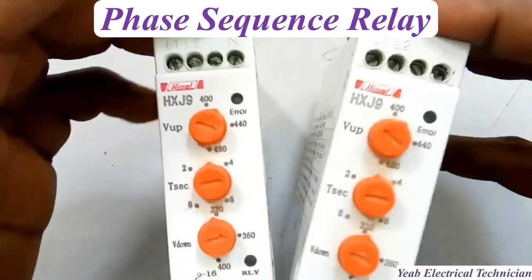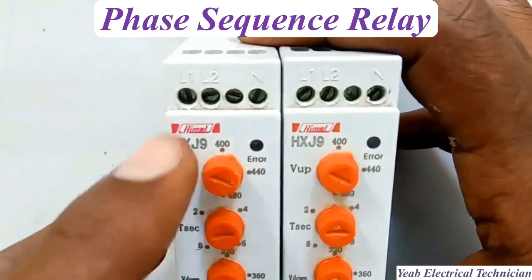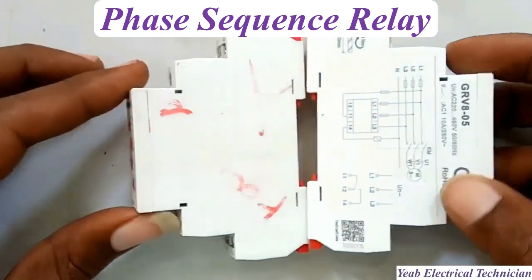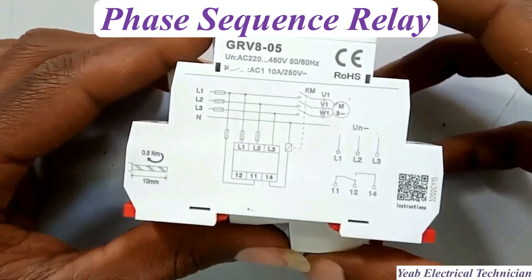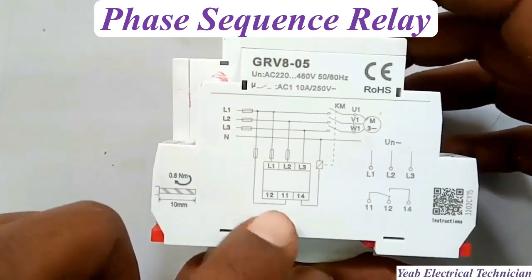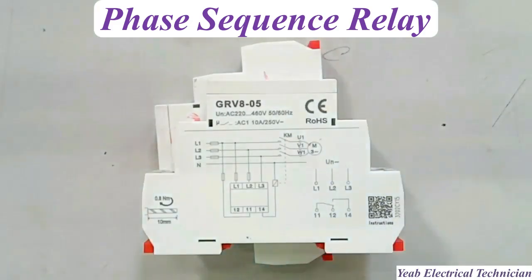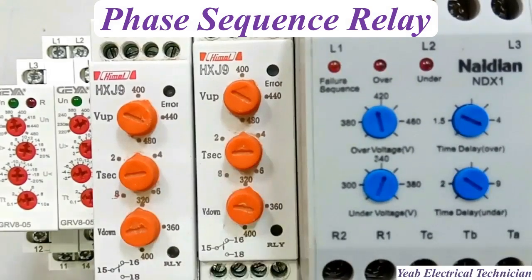It ensures that the three phases, line 1, line 2, and line 3, arrive in the correct order. If the sequence is wrong, the relay trips to prevent the motor from starting, avoiding damage and protecting against reverse rotation. It detects if one or more of the three phases are missing from the power supply. It can also detect if the voltages in the three phases are not equal, which can cause a motor to overheat or malfunction.